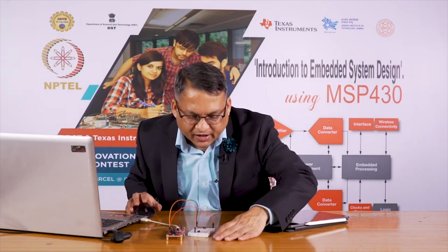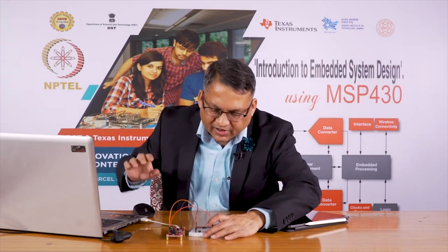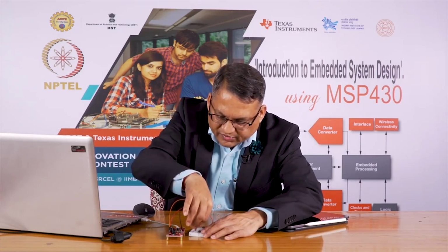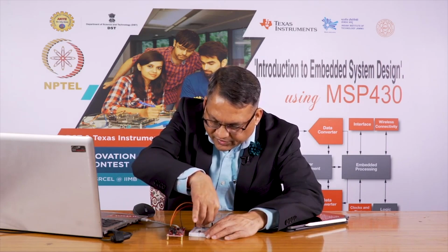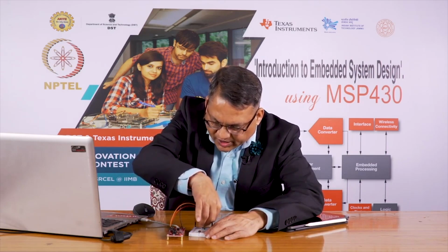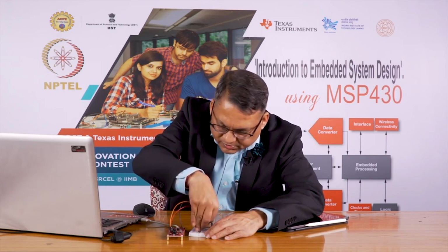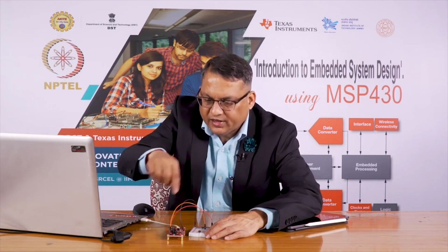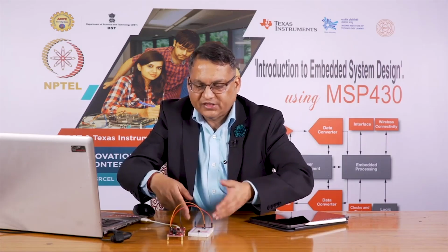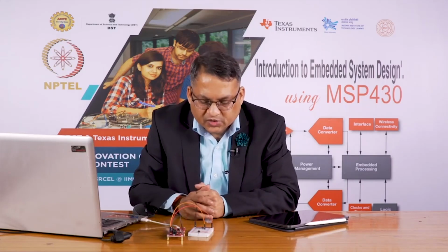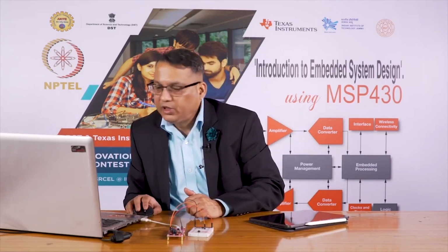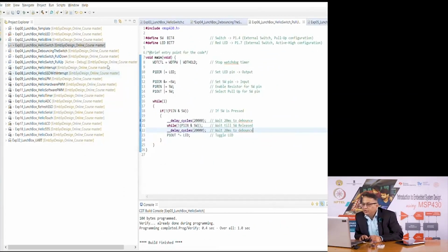I will connect the appropriate switch, the one configured for pull up, and we will recompile this program here. There are two wires, one to ground and VCC, and the third wire is to an appropriate switch. In this case the switch is such that it is a pull up configuration. So, we are going to use the internal pull up feature.